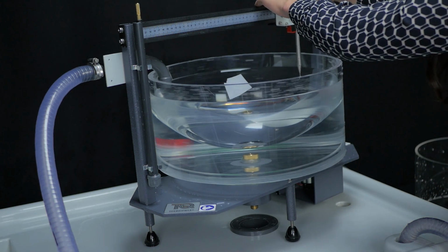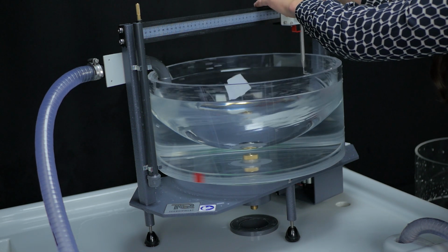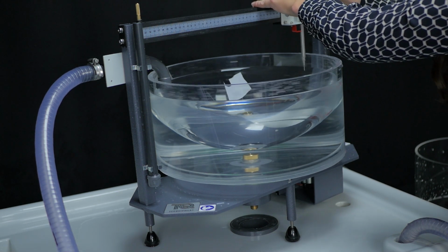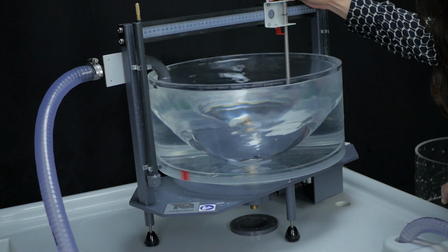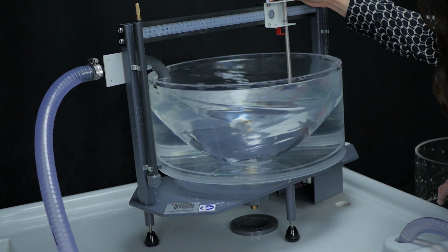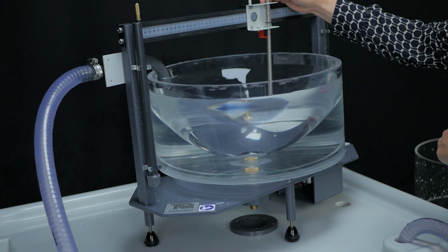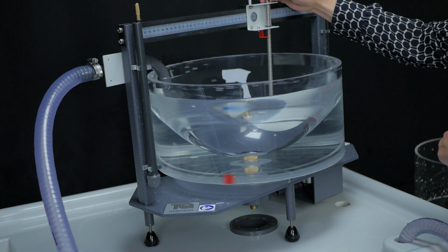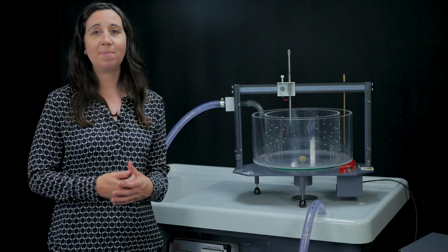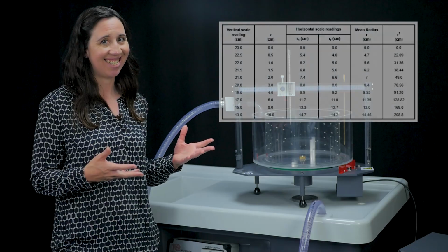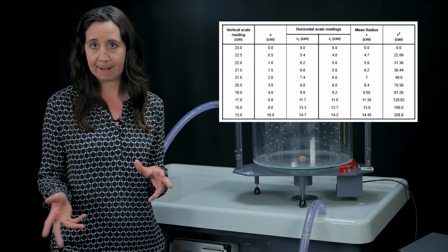After a few minutes, the vortex becomes constant, and you can measure the surface profile using the traverse probe. This can be moved both horizontally and vertically, and both axes have linear scales. Students can also measure distribution of total head by replacing the traverse probe with a pitot tube. You want to be taking about 10 recordings to get a decent data set, as shown here.